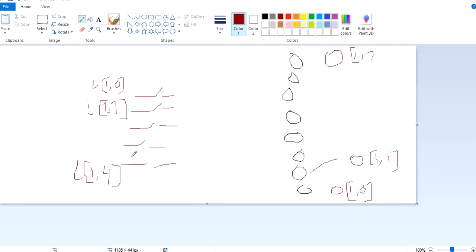So input 0, input 1, input 2, 3 up to 4. Okay, so we have 5 inputs, and we have 8 outputs. O10 to O17, 1 is the card address, as I said, and I10 to I14. Okay, 1 is the card address and these are the input numbers. These are the push buttons.